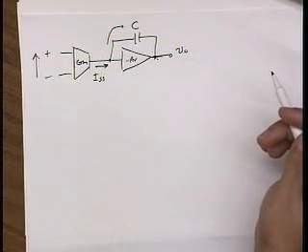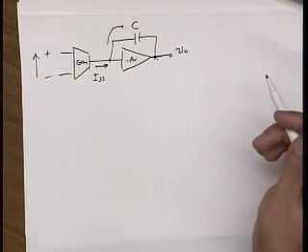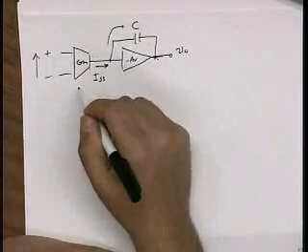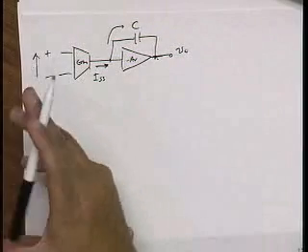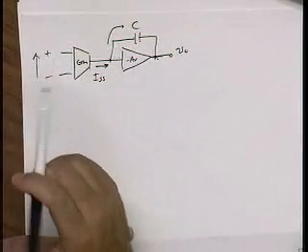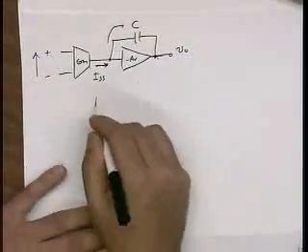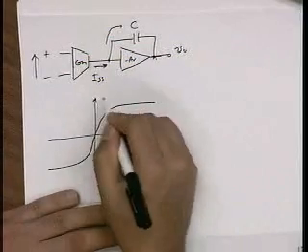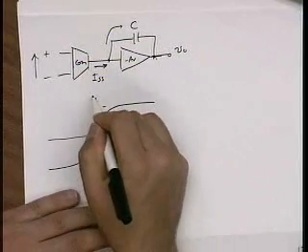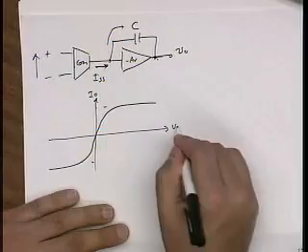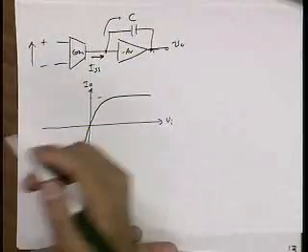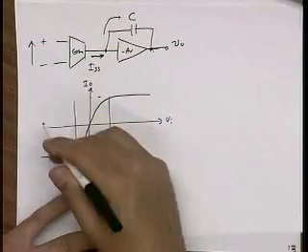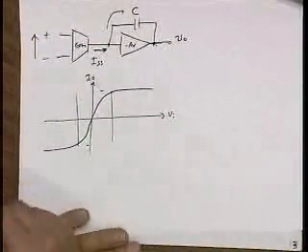So the question you're probably thinking about is, how big of an input voltage do I need to apply in order to observe this? And if you basically just plot I out over V in for your transconductor, you have the answer. So for instance, if it's a bipolar device, this curve looks like a hyperbolic tangent.